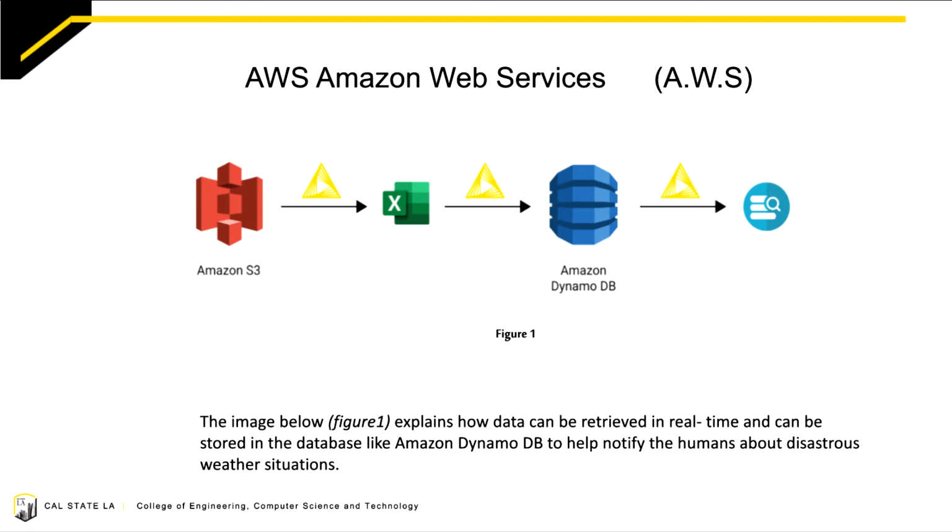First, we have the agreed upon required components. Station 3 is designated to be an indoor station. With this in mind, we selected 3 sensors that can detect harmful indoor and contained gases. Our CCS811 sensor detects carbon monoxide, metal oxide gases, and volatile organic compound gases. The MQ4 is designed to detect several combustible natural gases, such as methane, liquefied petroleum gas, and hydrogen gas. Finally, our PPD42NJ sensor is capable of detecting the concentration of dust particles in the air.